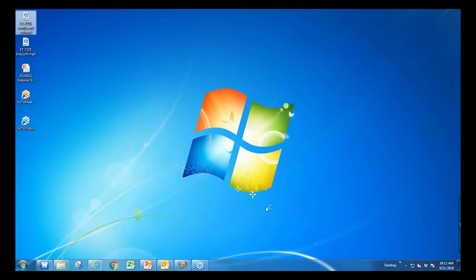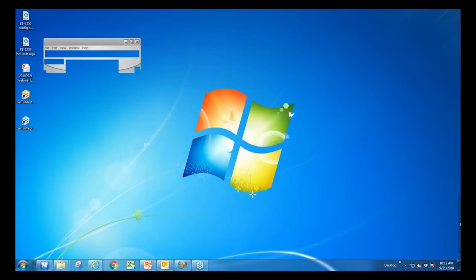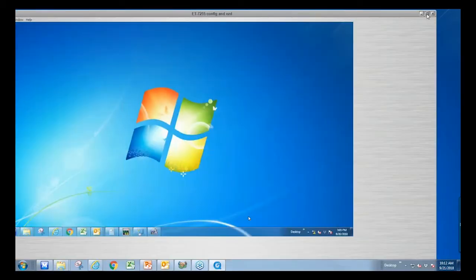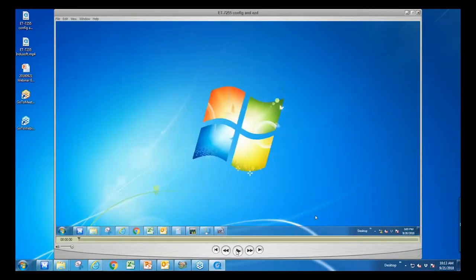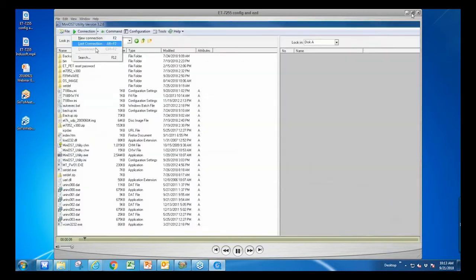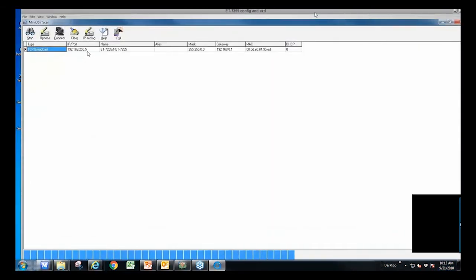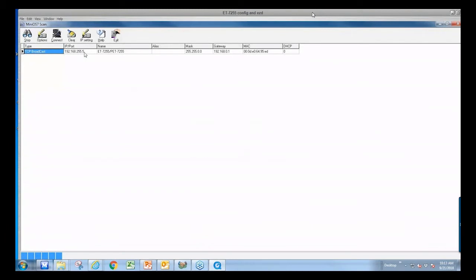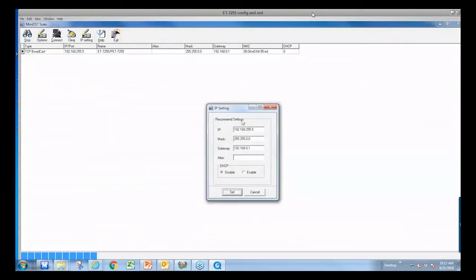This is just an illustration showing our PET models. Again, for our PET 7000 series, it's only got one port, so you can connect it directly to a PoE switch for PoE power. For the second picture, the PET 7200 series, PoE power is only applied to the first module. Only Ethernet communication is passed using the output port or second Ethernet port.